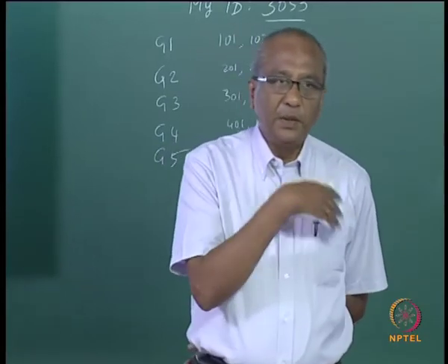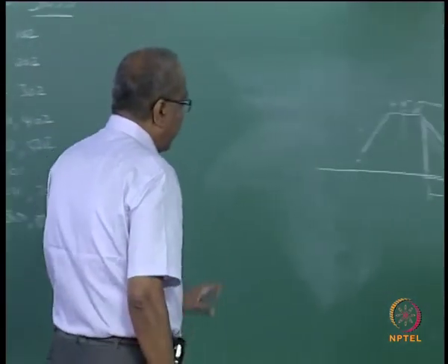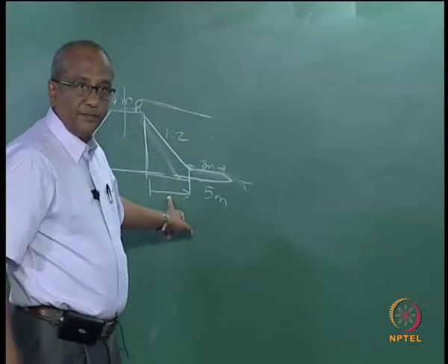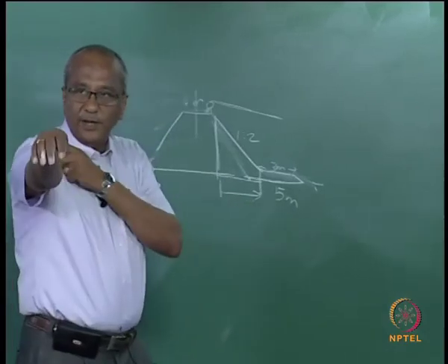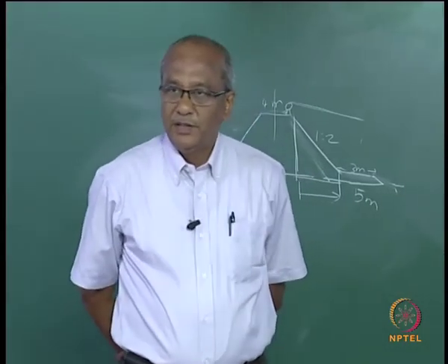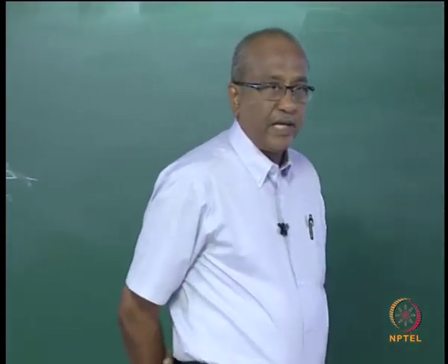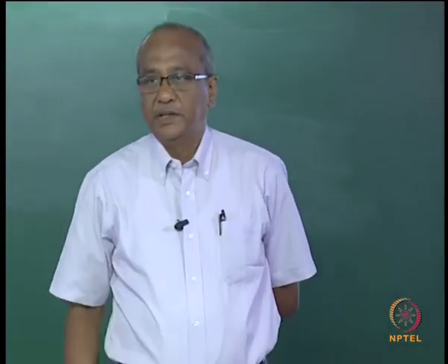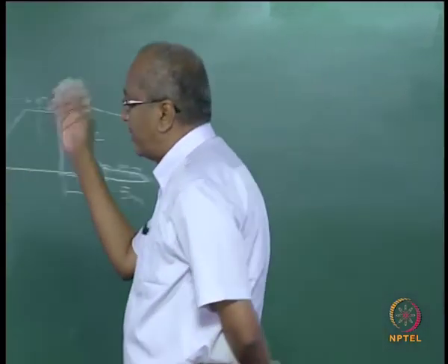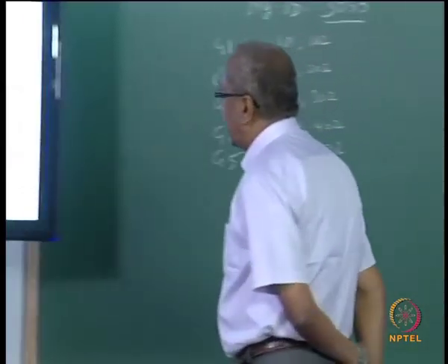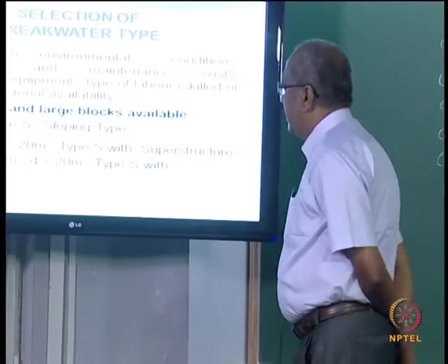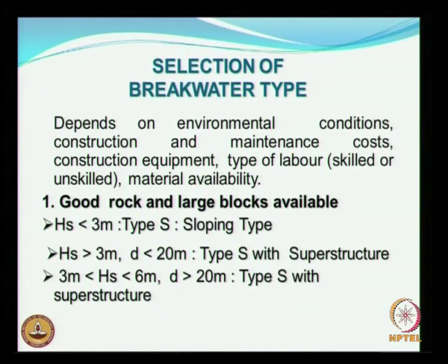But same thing, you imagine that you are running in at 10 meters water depth, then your boom length becomes more. And getting such a kind of a crane becomes a bit difficult. So all these aspects have to be looked into before you really get started with the construction. So under this selection, where you have good rocks and large blocks available, that is the area where you can just simply go in for this kind of a breakwater.